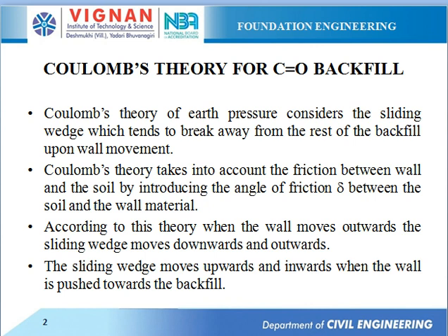Generally, a few theories like Rankine's theory are restricted to only homogeneous soils with a smooth back surface of the wall and to limited soil types, but Coulomb's theory can be used for all kinds of soil masses for determining the earth pressures.